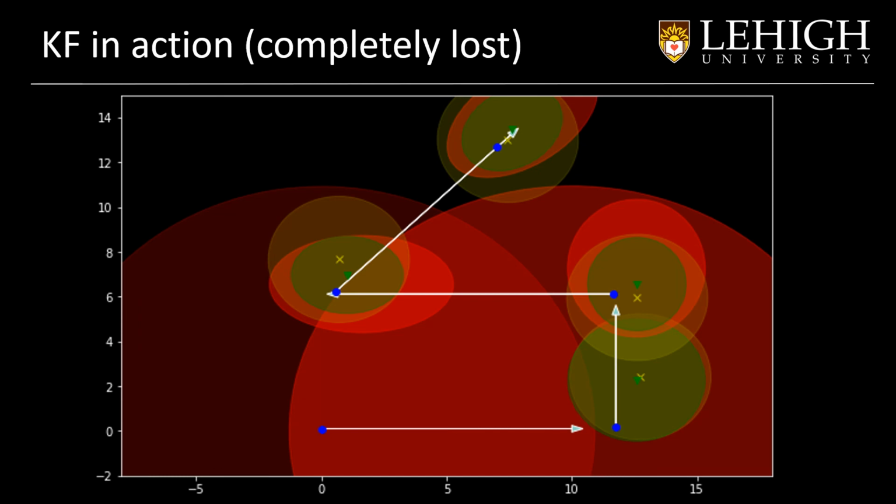If we have a case where our initial estimation is really bad, like we have no idea where we are in the environment, we can make the initial covariance matrix very big, such that the error will be huge. We can place them everywhere. Say this is the real robot and our initial estimation is there, but we have no idea where it is.